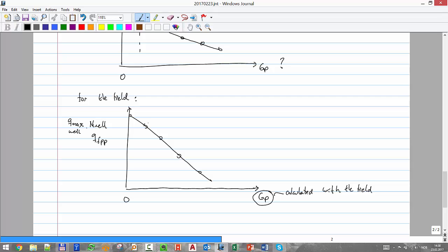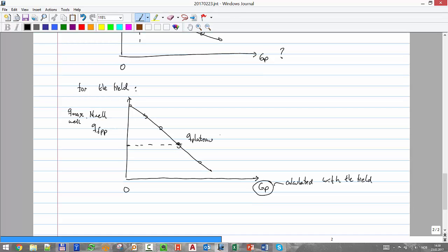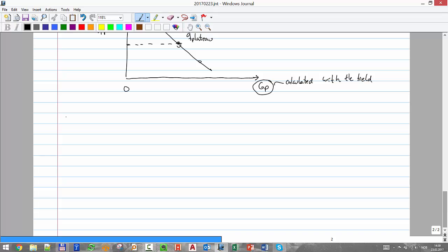So okay, you say we understood what is production potential, but why are you talking about it? For example, if I have a plateau rate, let's say that is here. That's my plateau rate I want to produce from the field. If you remember, how do you find the end of the plateau? What is the procedure you have seen so far? When it's full open choke? No. Remember, in plateau I'm choking all the time, right?